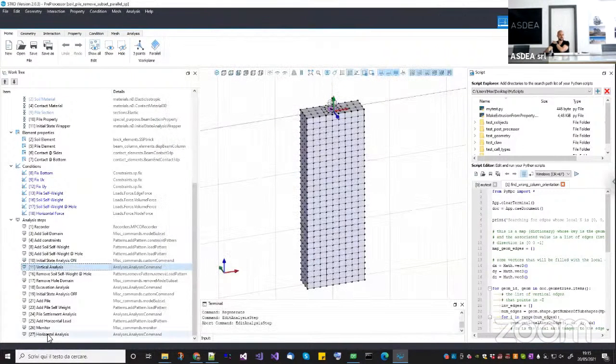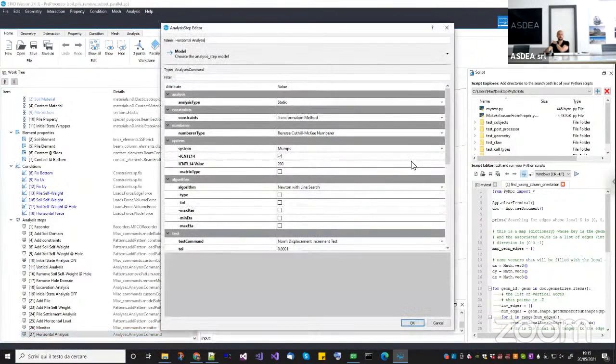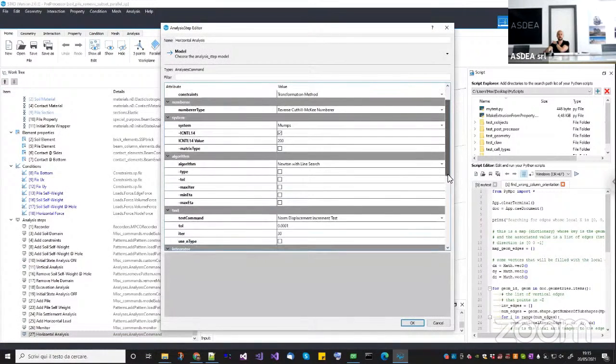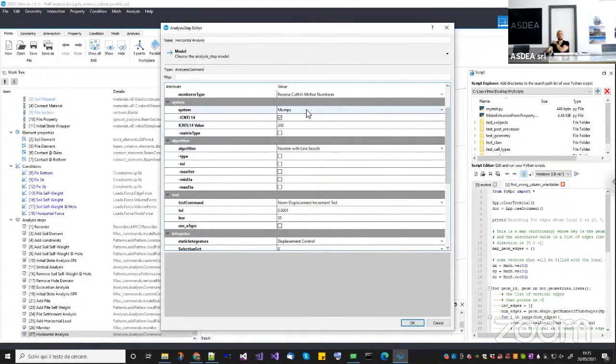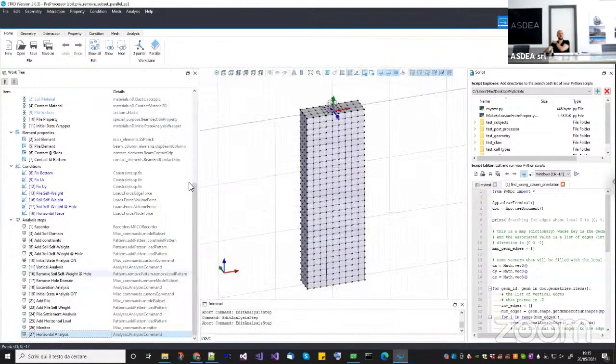And also in the displacement control analysis, the only thing that you have to change for OpenSeesSP is the algorithm. The displacement control is the same. Then once you do these small changes, you go into the analysis and choose OpenSeesSP. When you choose OpenSeesSP, you can choose the number of processors. So let's say I want 4 processes, and I run this analysis.